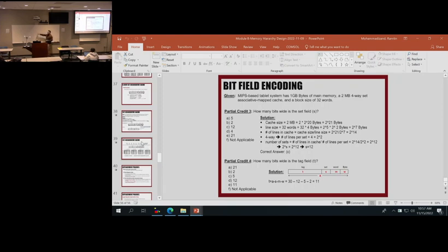So when you have 0, 1, 0 as the input, only the second line will be activated, and everything else will be 0. So if you have a 32 bit address, it's going to be a 32 to 2 to the 32 decoder. So only one of these lines is going to be activated at a time.